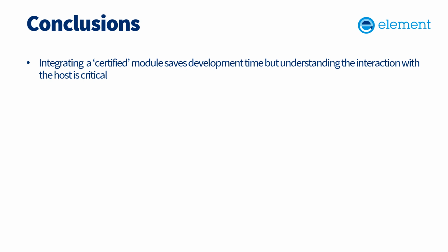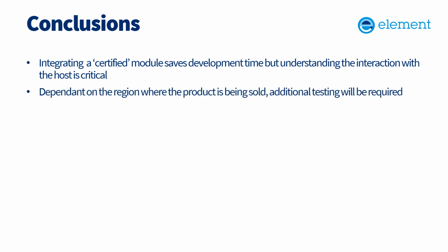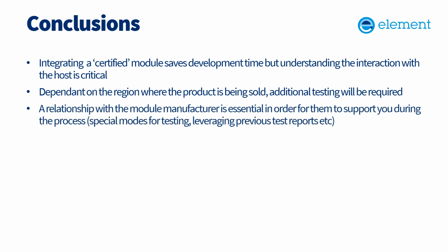So in terms of wrapping up then, integrating a certified radio module saves development time, but an understanding of the interaction with the host is absolutely critical. Depending on the region and where the product's being sold, additional testing will be required when you integrate a radio into a host.